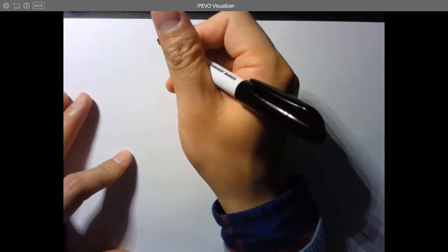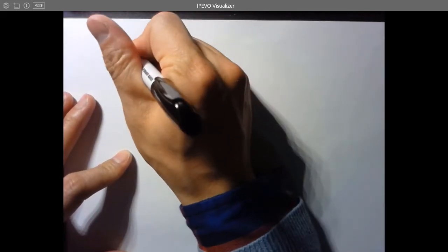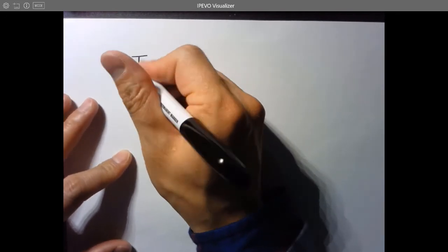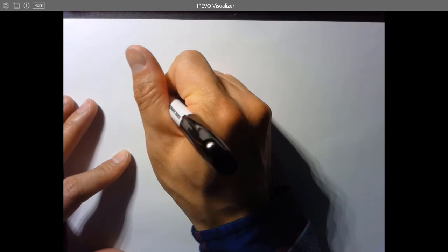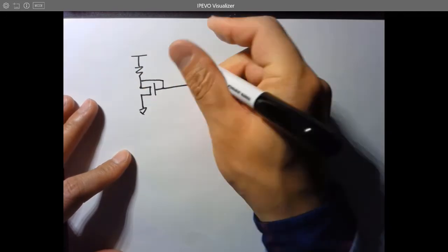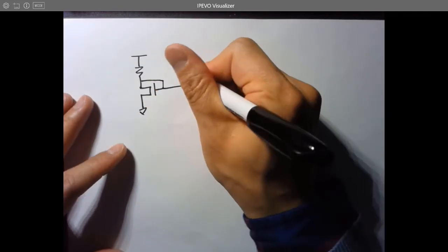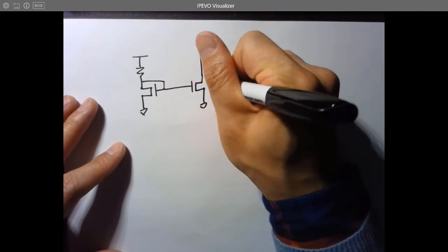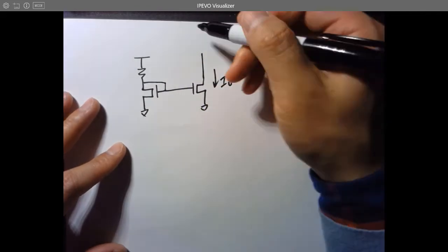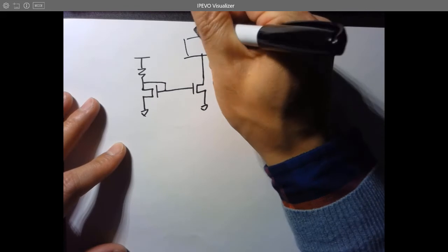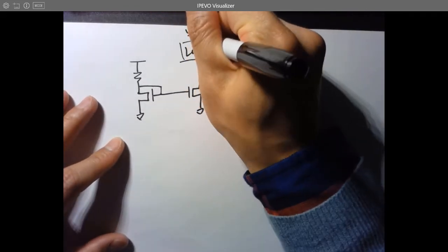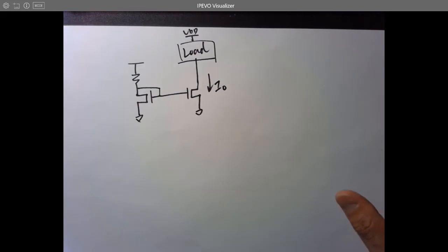For the current mirror, we introduced the first one at the very beginning, which has a voltage source and a resistance, which is trying to bias your reference NMOS, and this VGS is going to be passed to this output stage and draw a current from the load. So the load is powered up by VDD as well. You'll need a voltage source, of course. So that's the original version, right?